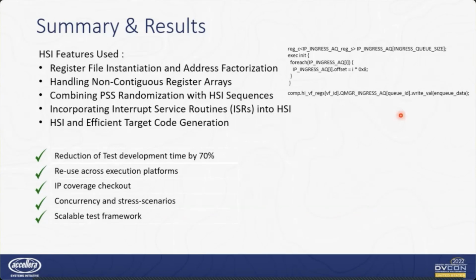And the thing with HSI is that it blurs the distinction between your driver code and your test code. Typically you would have UVM sequences, and then a UVM test which calls these sequences. Or in the C world, you write a driver, and then you have a test case which calls these driver functions. But with HSI, the distinction is pretty much blurred. It's basically a single file which is the driver and the test case in a way.